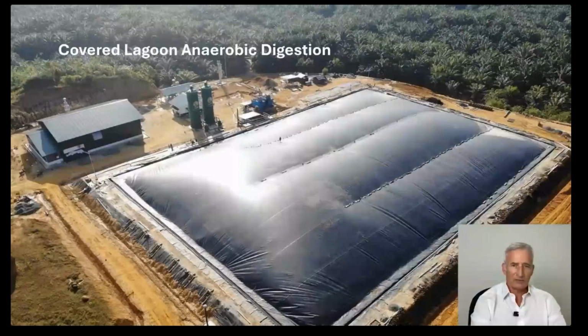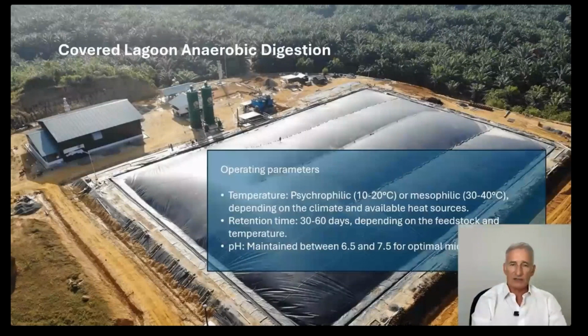Operating parameters include that it can operate between 10 to 40 degrees centigrade, depending on the climate and the availability of heat. But of course, this has a direct effect on the retention time, which can be between 30 and 60 days, depending on the feedstock and the temperature. The pH is maintained between 6.5 and 7.5 for optimal microbial activity.